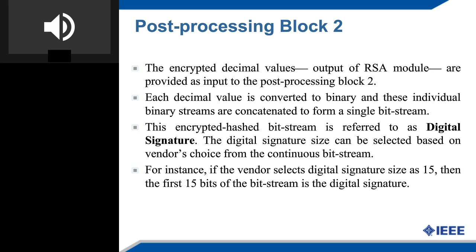Bit 1 represents that an artificial edge is added between even node pairs in the CIG, or colored interval graph. These two different forms of artificial edges are added into the CIG of the respective DSP design in order to implant the secret constraints. Finally, these constraints act as a watermark in the register allocation step during HLS. These hidden constraints are additional constraints imposed on the design besides the regular design constraints that exist.